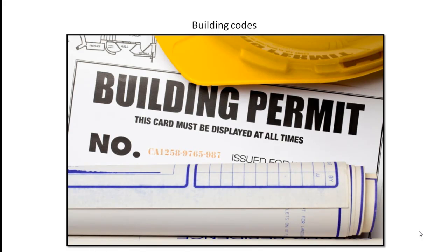Building codes. Building codes are a detailed set of regulations that apply to how buildings are constructed, modified and repaired. Building codes set the rules by which the various trades must operate. They stipulate equipment and materials that can be used and how they must be installed. For example, they stipulate the maximum voltage at which PV systems can be wired and the use of safety measures such as disconnects.